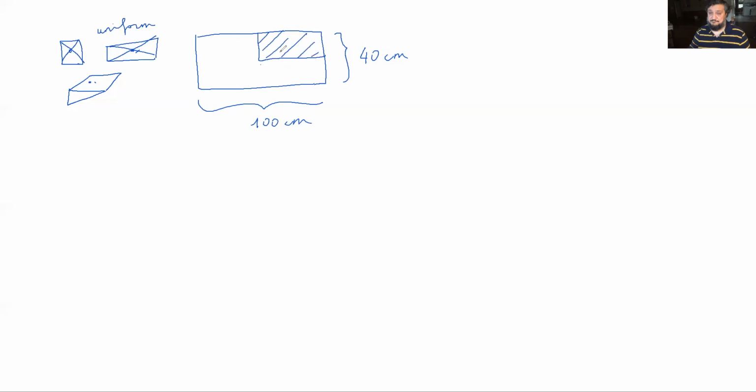Now, before you cut it, the center of mass was the geometric center. Now we have this L shape, so you expect the center of mass to shift to here. But where is that point exactly? Let's try to find that. It's our problem. Where is our center of mass?